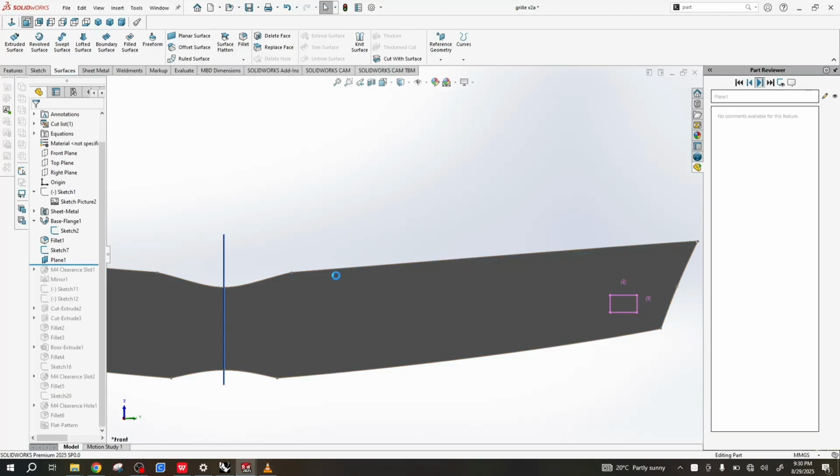That's about that. And then I used that pink sketch to make the slots. This is another thing: when you're prototyping, try and use slots as much as possible. Don't use fixed holes, because slots allow you some bit of wiggle room on either side. If you have a hole, you're fixed, you need to commit. You can start with the slots, and then after you're sure about what you're doing, that's when you move on to the holes.